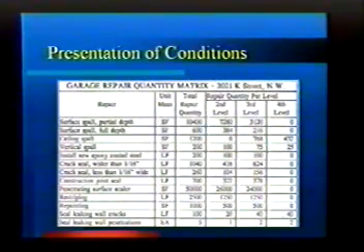Here's a little bit of a trick. What we do is we add up the quantity per bay. So for instance, in this bay, I've got 285 square feet of delaminations. Some people may mark it on each individual one, but we do it adding it up per bay. Now we can add all of that up, and we have a matrix of all of our findings.